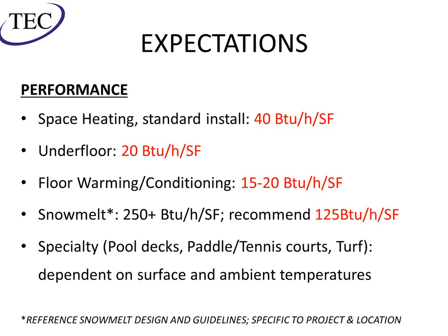In a snow melt system, since you're dealing with much lower surface temperatures and a bigger delta T, not necessarily a bigger delta T in the water system, but between the surface of the concrete and the air, you can definitely shove a lot more heat into that slab. You can go over 250 BTUs per square foot. In the Chicago area, regardless of the application, for the most part, 125 BTUs is not only acceptable, it's a very good number to use for estimating.